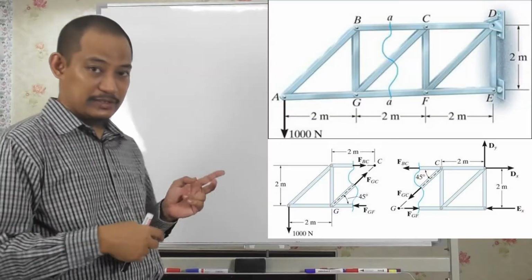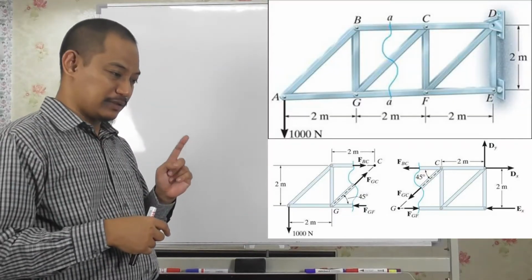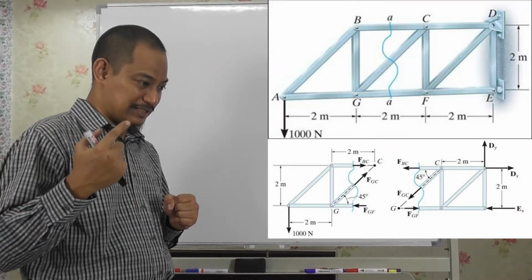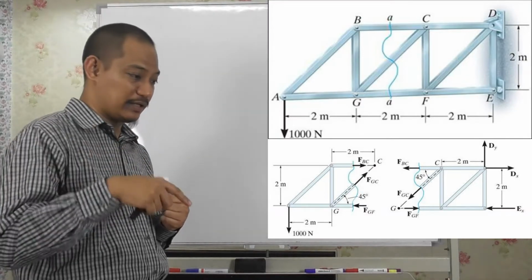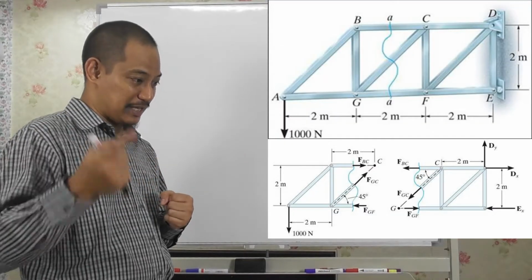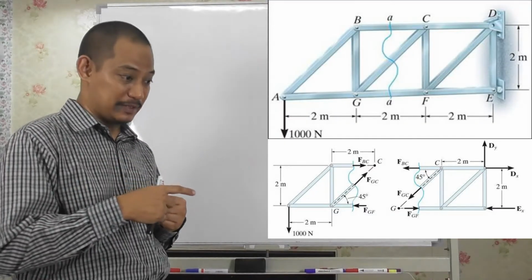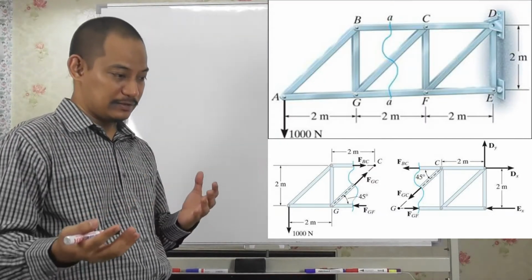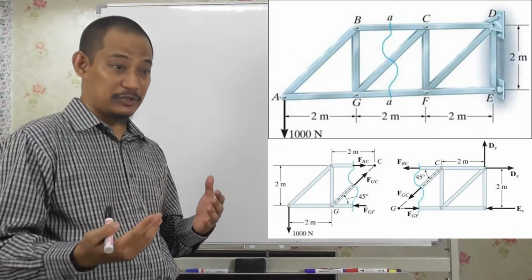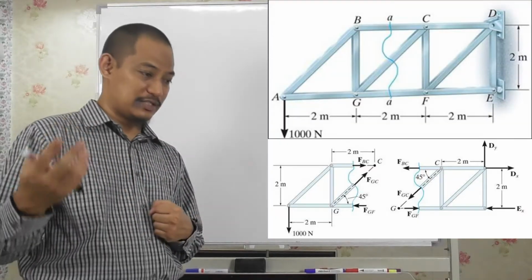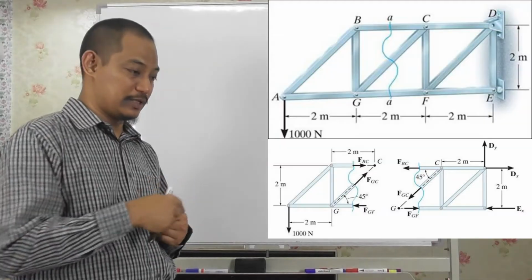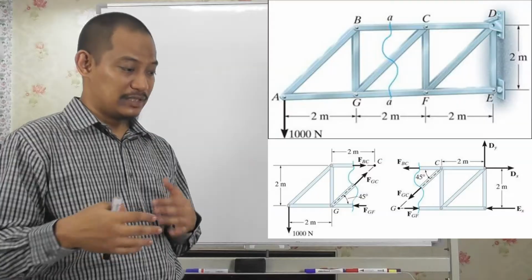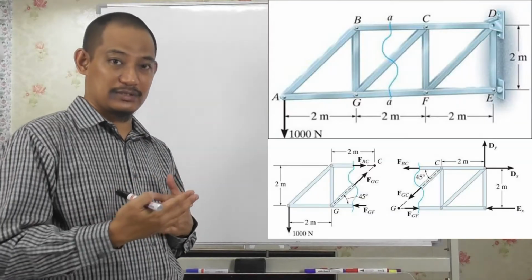But in this diagram here, if you see, the left side actually draws FBC, FCG assumed to be in tension, while FGF is drawn in compression, right? So you can see that the right side is the same in the sense that it is just corresponding. So 2 forces are assumed to be in tension, 1 in compression, as shown there.